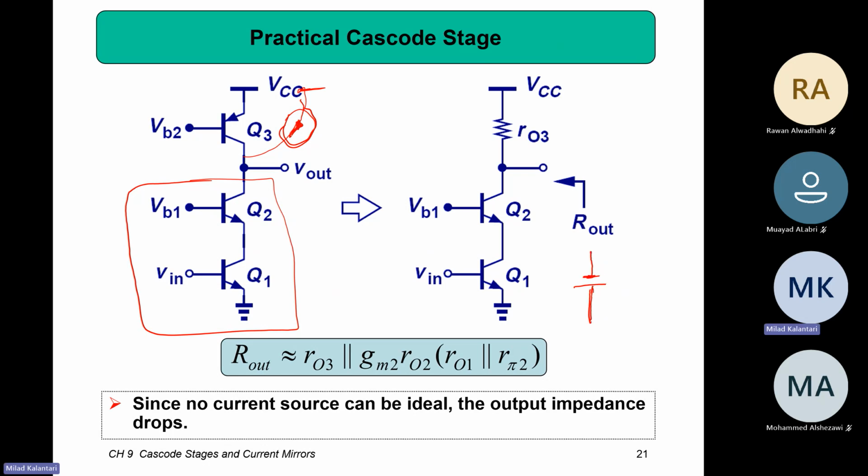What kind of resistor? Where? Is it series or parallel? If you put a series resistor, this is a way, because we know that this has another Norton model. This is a Thevenin, so you can model it with the Norton.